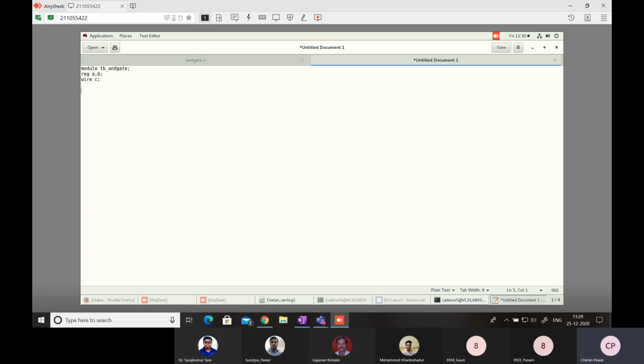So for that purpose, first we need to give the instance component name. This is also called a component instantiation, meaning creating an independent copy of that component. So I am taking AND gate. So first I am mentioning AND gate. Okay. So this is the AND gate. Okay. And U1 is its copy. Okay. That is a copy of that AND gate. Right. AND gate U1 bracket.